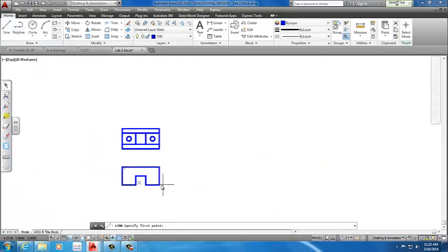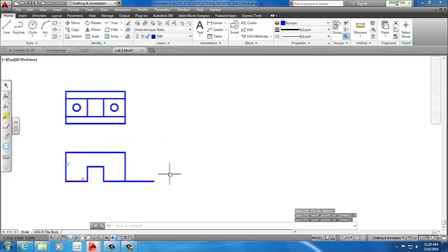It's up to you how you want to do that. If you want to start with where to place my side view, I'm going to do a 2 inch gap, which is usually what we want to do. So you can call it the center, and then we're going to start drawing from this point, specifying the distances, diameters, and radiuses. We're going to go across 0.5, and then go down 1.25.